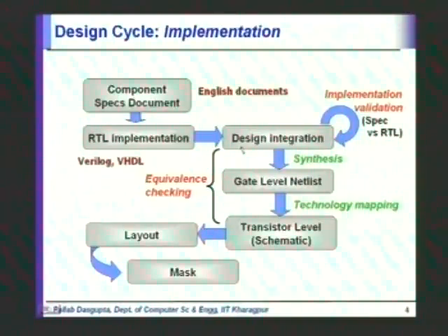So there are several approaches which are taken. One is that you could have a previous implementation which has the same functionality but a different architecture. You could use that and compare its results with the results of your simulation. The other option is that you had that C-spec model in the previous slide, and that also is going to give you, at certain points of time, the expected outputs. You could use those outputs as the golden outputs and compare them with the outputs of your simulation.